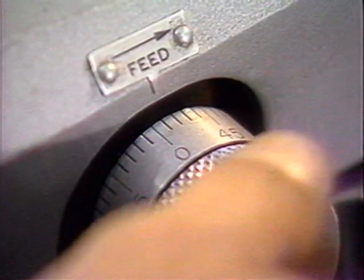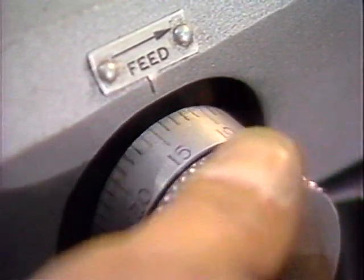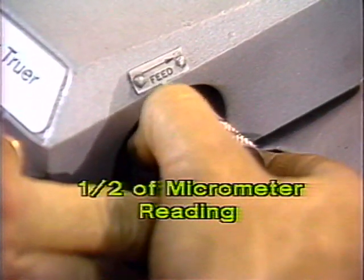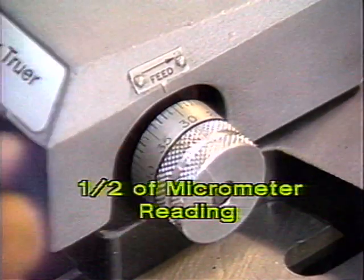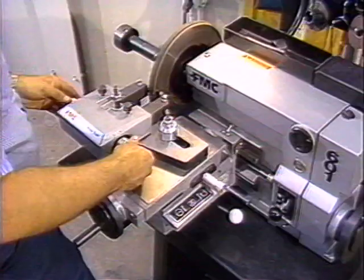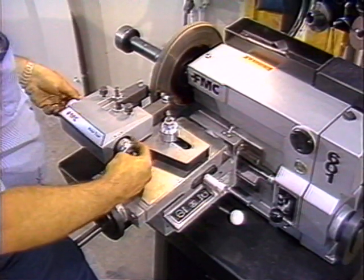Turn the lathe on. Locate the right depth wheel until the cutter tip on the right side just scratches the surface of the rotor. Set the micrometer dial to 1/2 of your initial micrometer reading. Repeat this procedure on the left side as well.